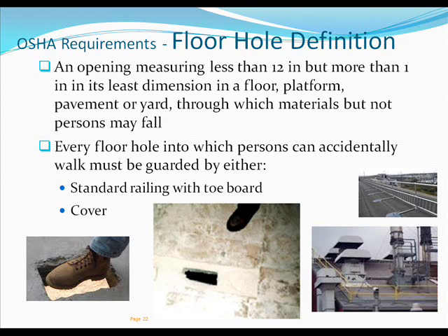or cover. Each employee walking on working surfaces must be protected from falling through holes, including skylights, more than 6 feet above lower levels. Each employee must be protected from tripping or stepping into holes, including skylights, by covers. Each employee must be protected from objects falling through holes, including skylights, by covers. Smoke domes or skylight fixtures are not considered covers unless they are capable of supporting, without failure, at least twice the weight of employees, equipment, and materials that may be imposed on it at one time.